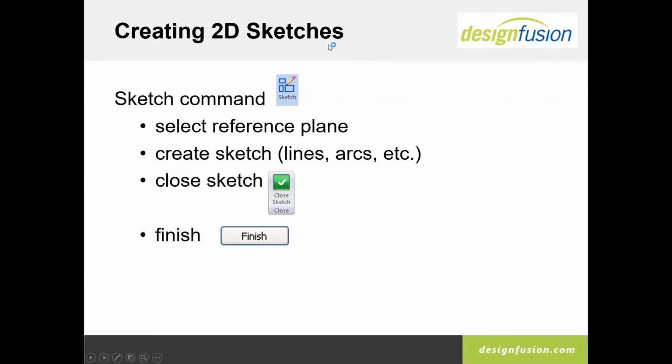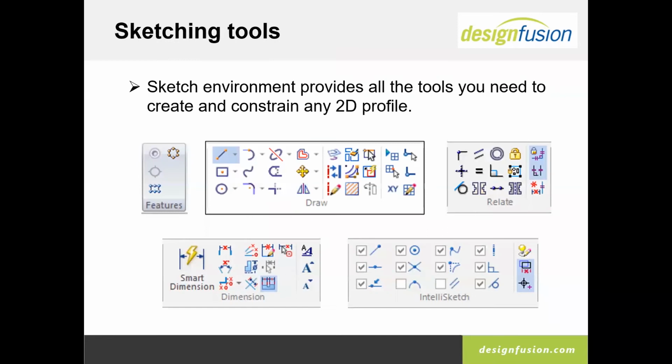If you're not going to do a sketch, you're going to use the profile, you pick the command such as extrude, and then select your reference plane and draw your profile embedded into the extrude feature. And again, it doesn't matter which you use, both of them will take you into the same sketching environment and provide you with the same commands to create your 2D shape.